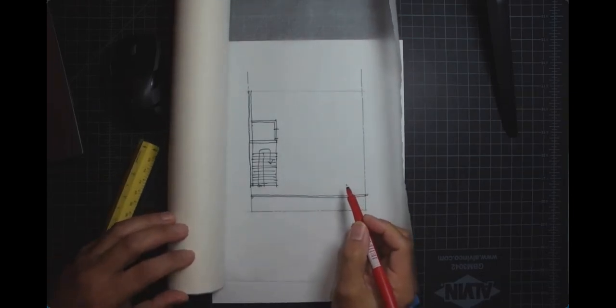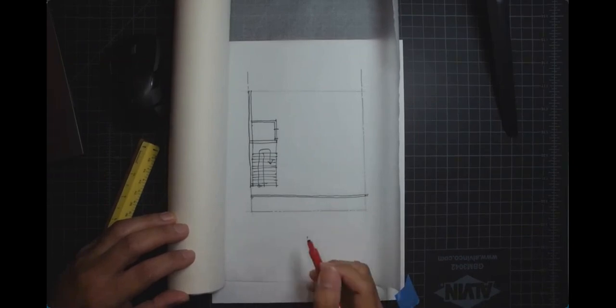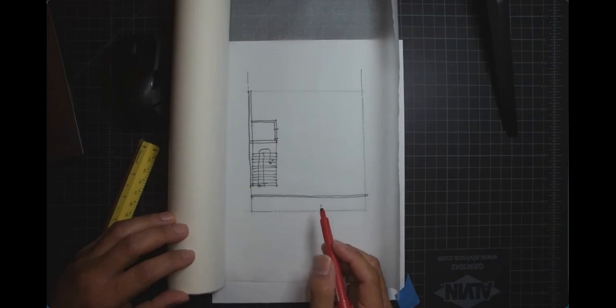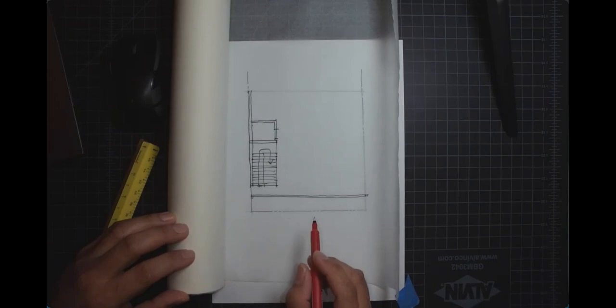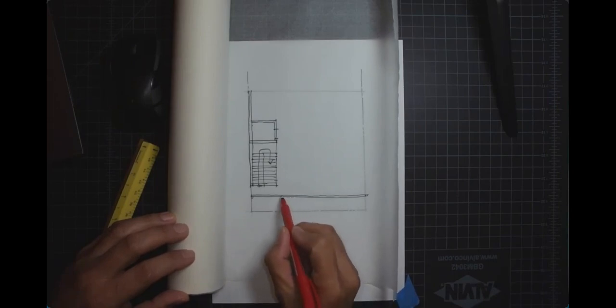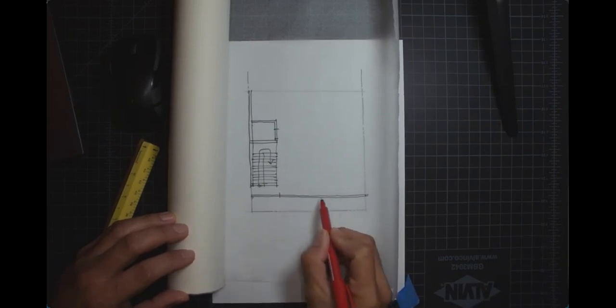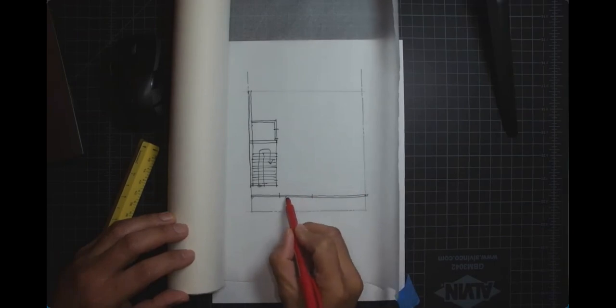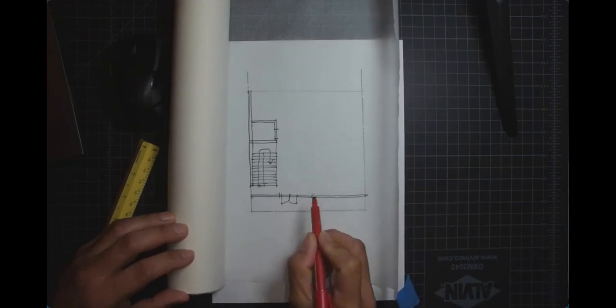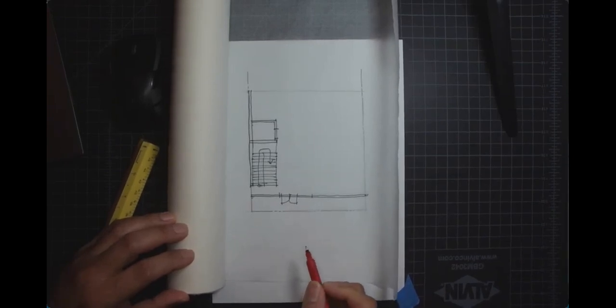So you can locate the doors. The doors must be 36-inch minimum, but in cafes you may want them wider. You may want them to open here or in the center of the building or wherever. If you want them to open here and you want them to be double, that's how to indicate that as double.